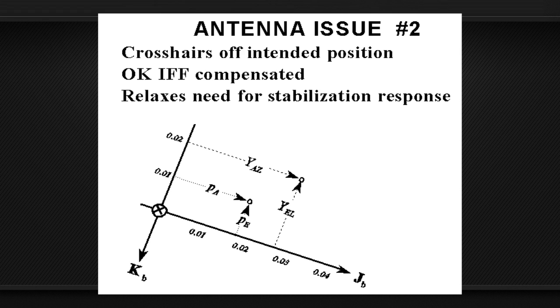For those with a copy of my 2007 book, the accompanying sketch matches figure 9.2 of that. In any case, though, it's easy to understand. First, let's take into account how stabilizing a radar beam implies a consistent direction spatially. If, for example, the aircraft pitches up, then, relative to the airframe, the antenna has to be steered down. More general rotations will cause the crosshairs to have some skewed direction relative to horizontal and vertical directions, and relative to airframe axes as well.